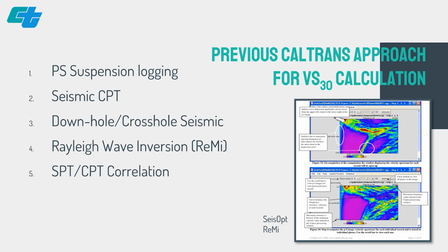Downhole is, for all intents and purposes, the same as seismic CPT and equally effective. And while cross-hole seismic is also effective, it requires 2 dry and stable boreholes, which is an added complexity and cost. Although valuable, CalTrans does not conduct downhole or cross-hole seismic investigations.